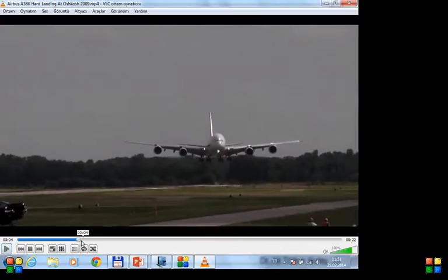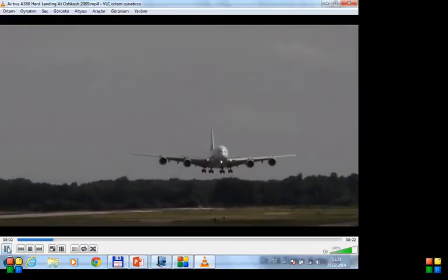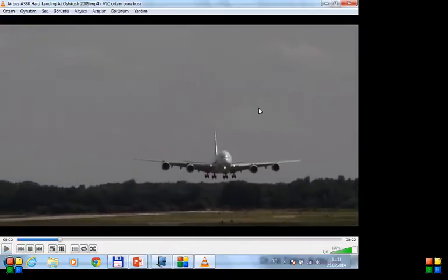Well, first you see that the aircraft is approaching in a funny way, right? It's not flying straight, obviously. This must be due to very heavy side winds. There are strong winds coming sideways, and the speed of the aircraft needs to be aligned with the runway direction, but under such heavy side winds, the aircraft nose has to be pointed that way.